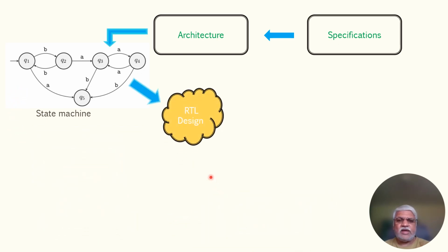So we need a different flow wherein the architecture is converted into a state machine as before. That means small modules should again be further divided into tiny modules, and then those tiny modules should be made into state machines that will be made into RTL design. For this, HDL code is used. This HDL code can be written in either SystemC or VHDL or Verilog.